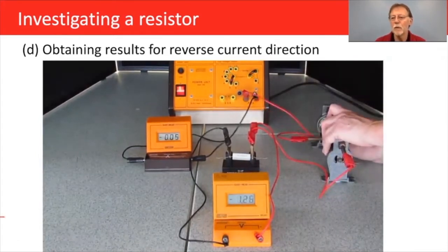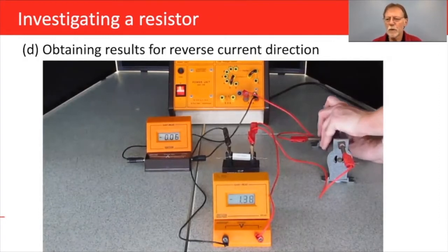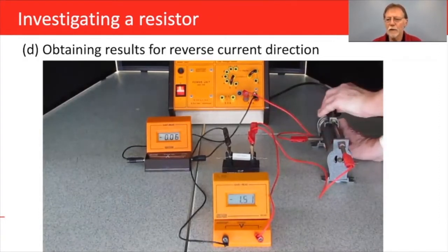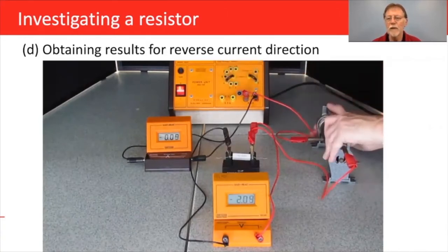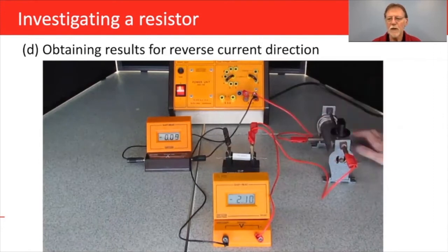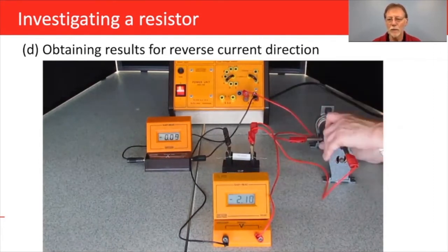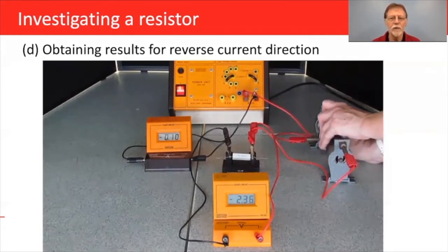As mentioned before, during the experiment, the resistor will get hot. Ideally, and to conform fully with Ohm's law, the power supply should be turned off and the resistor allowed to cool between readings. Resistors such as these, however, are made of a material where the resistance changes very little with temperature, so not allowing any cooling time has no noticeable effect on the results.